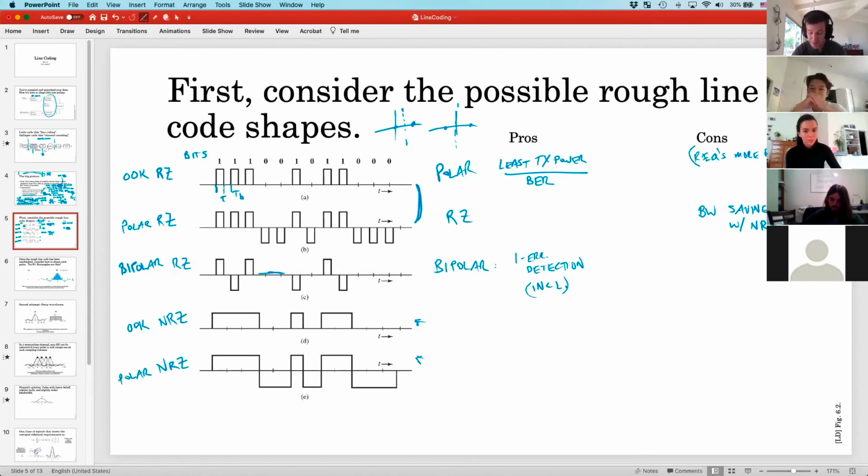Now those bandwidth savings are pretty much erased if you get 1 0, 1 0, 1 0, if you have lots of bit variation. So one could imagine that if this bandwidth savings was very important to you, you could put something upstream of your channel coder that favored sending like bits together. Okay.